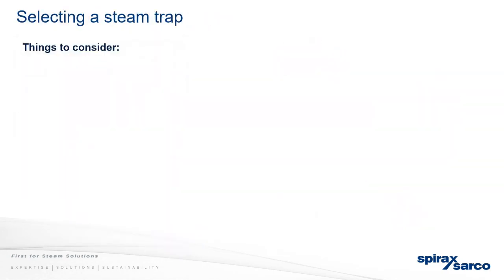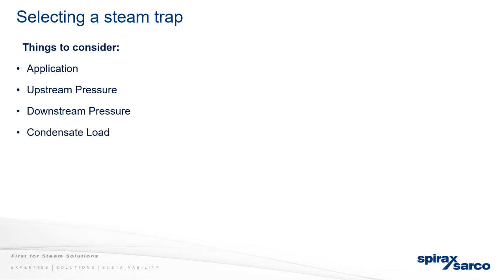So things to consider: the application, where are you going to install it? Upstream pressure and downstream pressure, so your pressure differential across the trap. Condensate load, how much condensate are you trying to clear? The materials required, and the connections you have. Risk of freezing. Again, my slides are a little bit European, so in Africa there's probably not much chance of freezing. Maybe in South Africa you guys do have freezing temperatures at times. And water hammer risk.